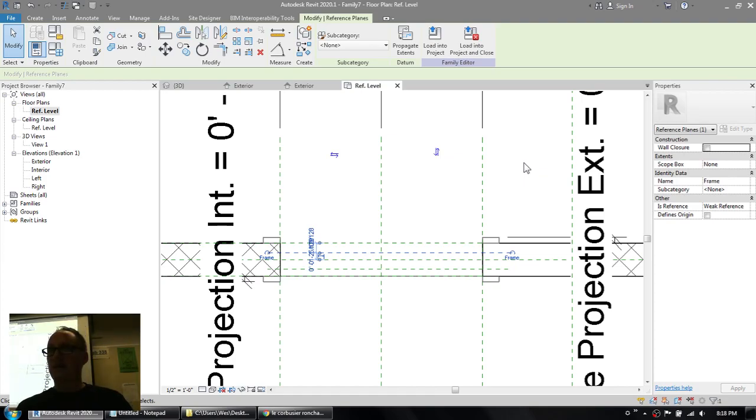As it says in the notes, note the origin feature and closure feature. Now, any reference plane in a door or window that runs parallel to the wall, parallel. So we're looking at the second bullet point on the bottom of page 5 under getting organized in 3 dimensions, after name the reference planes. 2 features. Origin, here. So I've got that reference plane selected. There's the origin feature. There's the wall closure feature. Now in your family, 2 of the reference planes will have the origin feature checked.